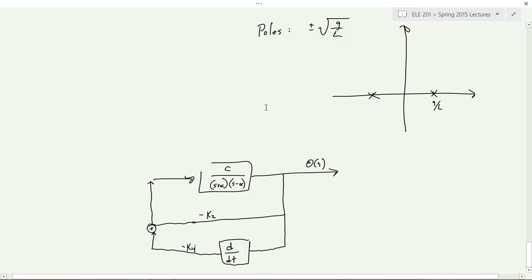So what I'll do is just plug in the other. I'll put in that feedback as well. All right, and so it's actually very common to use this control that uses proportional feedback and derivative feedback. And if you want a third parameter, you put in integral feedback. And this is known as a PID controller, proportional integral derivative. Very, very common, simple controller that's used to control a lot of things. So we're just using the proportional and the derivative part.